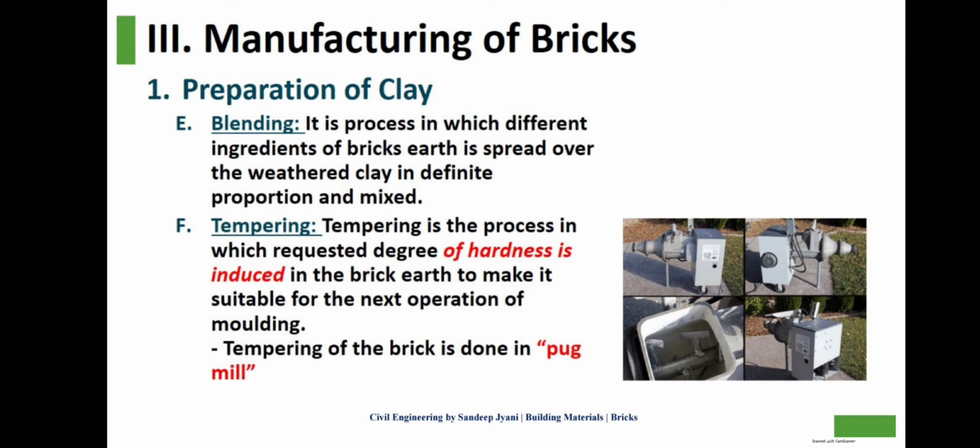Tempering is the process in which the required degree of hardness is induced in the brick earth to make it suitable for the next operation of molding. Tempering of the brick is done in a pug mill.